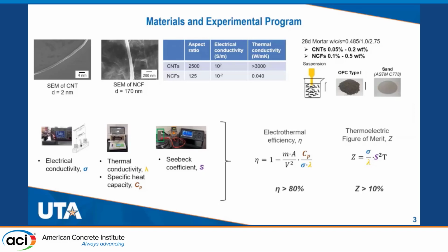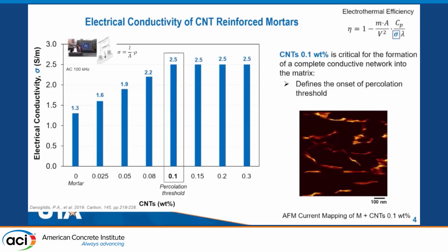To calculate the electrothermal efficiency and the thermoelectric figure of merit, we conducted measurements of the electrical conductivity, thermal conductivity and specific heat capacity, and the thermoelectric power, the Seebeck coefficient, for the thermoelectric figure of merit that I will talk about in the second part of this presentation.